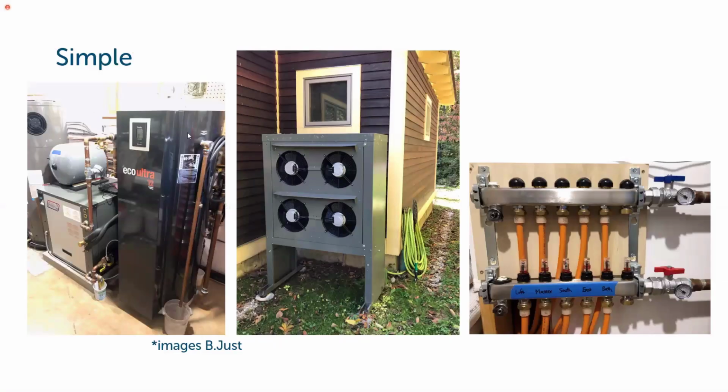So here's an air-to-water system. This was a retrofit actually installed by a colleague of mine over the past year in his own home. He went from a gas boiler that was feeding a radiant slab and then fin tube baseboard in the bedrooms on the second floor, to replacing the fin tube with low temperature emitters, some panel radiators in the bedrooms, utilizing the radiant slab, and putting in a Nordic air-to-water heat pump.